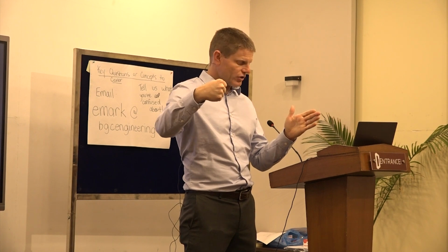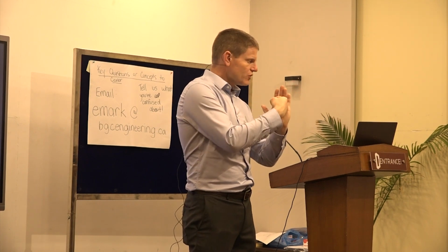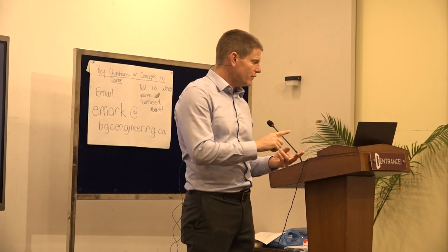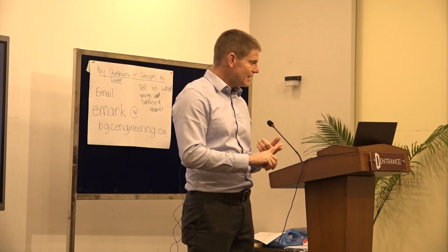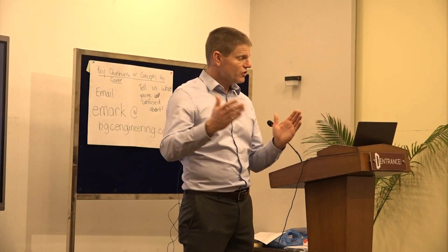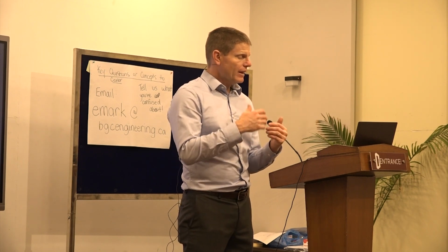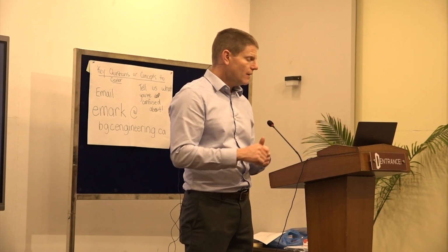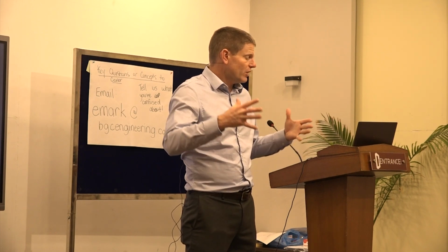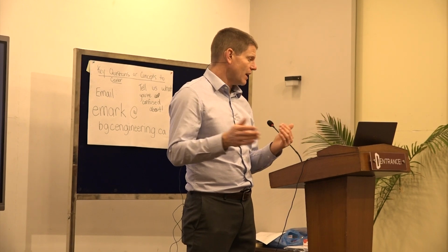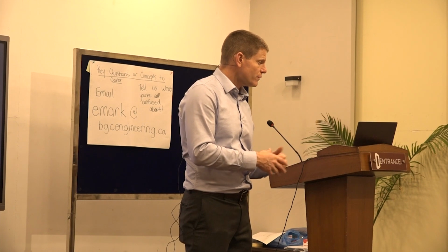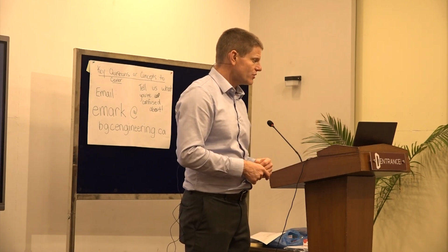So when you have the debris flow hitting the structure itself, the impact force depends on the velocity squared times the density of the flow. If it's purely water, then it has a lower density than a debris flow. And so that's the main issue. Also, debris flows tend to be very large discharge, so you have a high velocity with the debris flow. So there are accepted equations for that I can give you connections to.